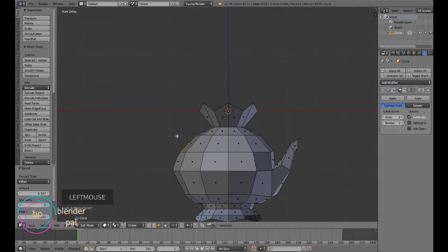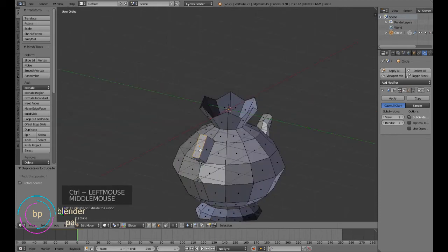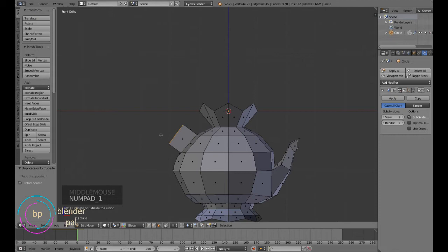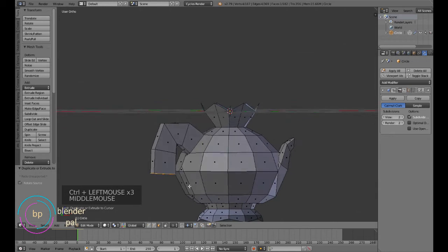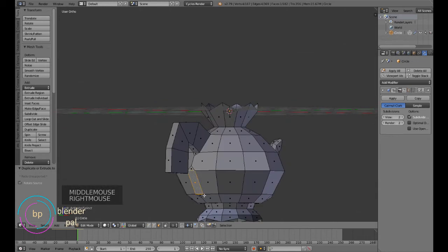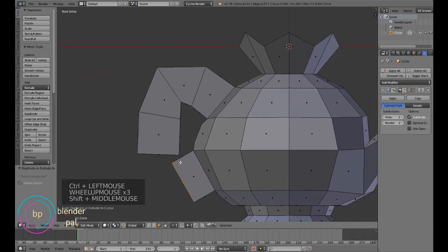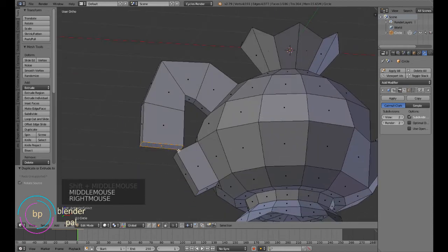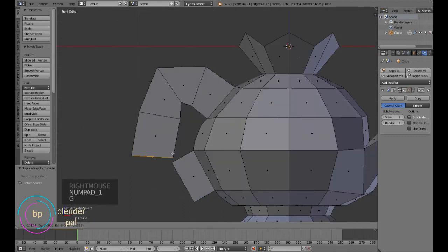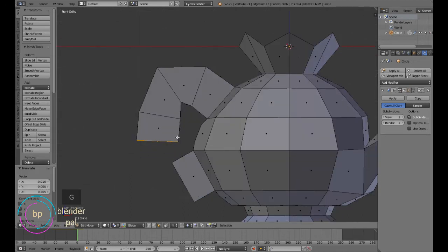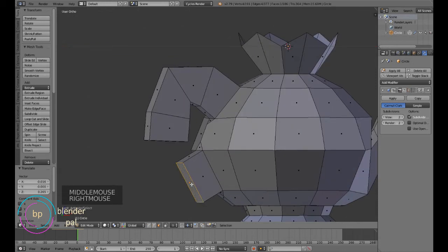If I'm holding Control and then left clicking anywhere, again it is extruded. Now this works like a charm, because all you have to do is go till there and then again select the down face that we have created by beveling it up and extrude it right about there. Then all you have to do is mix them, or better to say join them together, so that there won't be any problem at all.